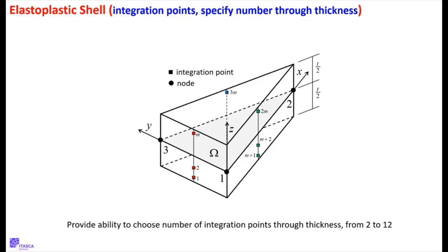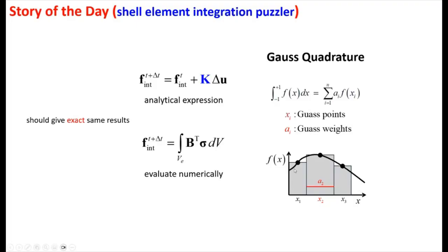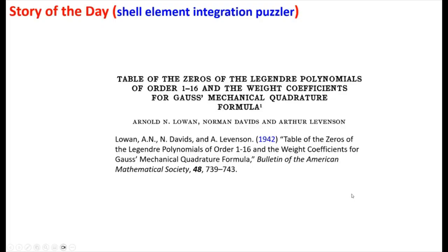And each one you use is going to have a different set of these points and weights. Here's using 3 points, and there's a certain location and a certain weight. If you used 4 points, there'd be different locations and different weights. So what this means is I had to find all of these solutions to the Gauss quadrature points and weights.